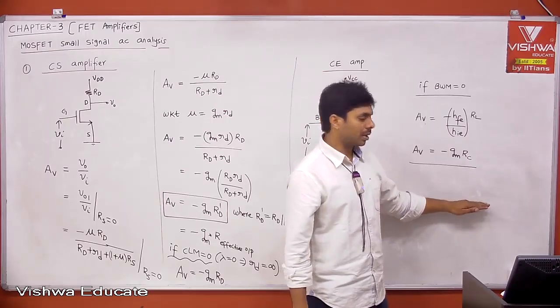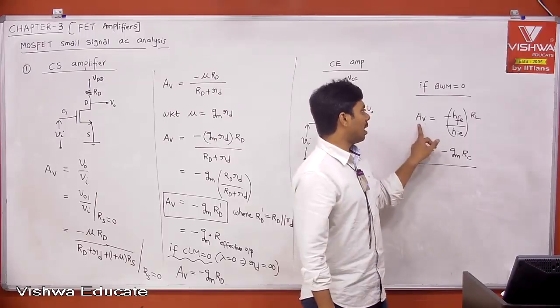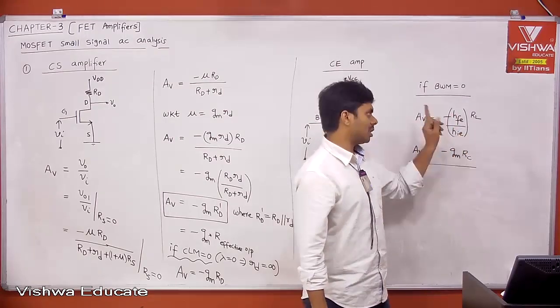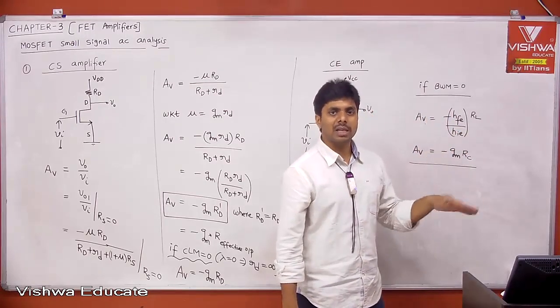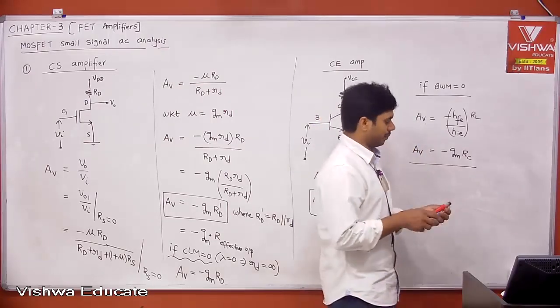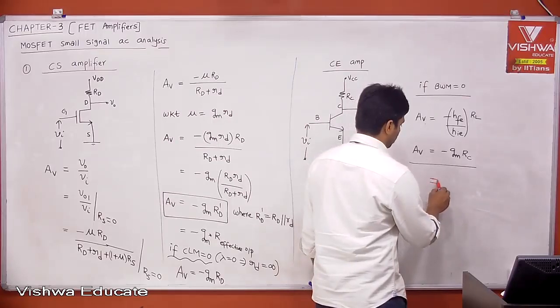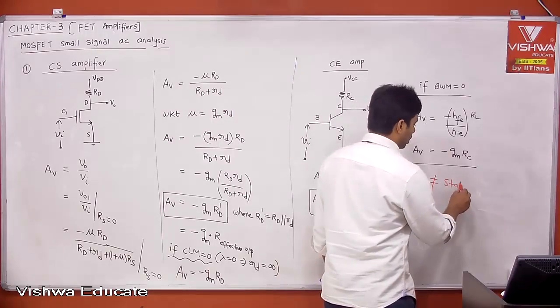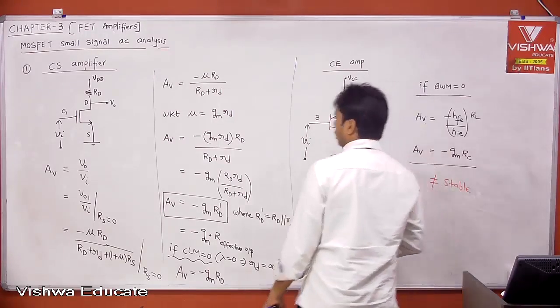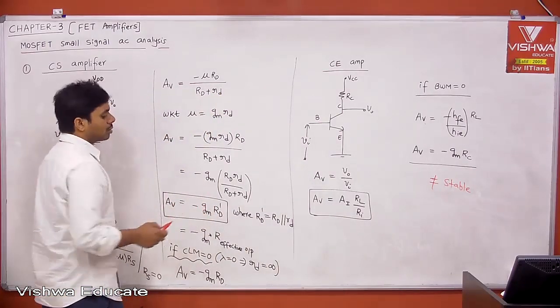Therefore again it depends on temperature. GM depends on temperature, so voltage gain depends on temperature. Or voltage gain depends on H parameters, and H parameters depend on temperature, time, replacement. Therefore your voltage gain is not stable. Similarly here, when I explain GM, GM is also not stable.